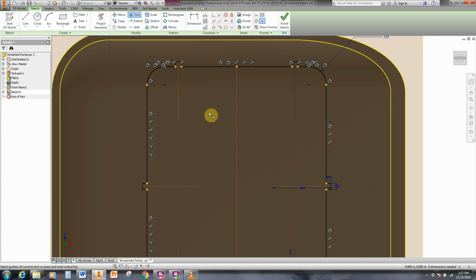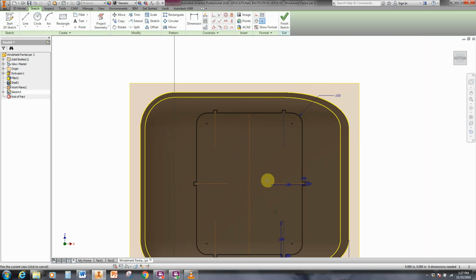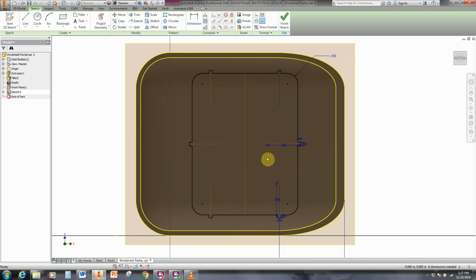I'm going to turn off my constraints. I could use the F keys, but instead I'm going to hit OK, and there they go. They're gone now. That is excellent. We're in really good shape. This is ready to extrude. I'm going to go ahead and finish part 3 at this point. And the next step, we're going to come back, we're going to extrude this, and we're going to shell it, and then we can change the material and change the color, and we'll be all done. All right, remember to save. Always save. Save, save, save.